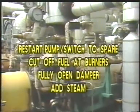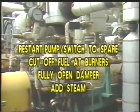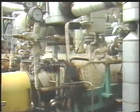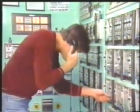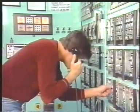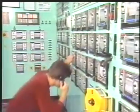Your first reaction should be to restart the pump if possible, or go to a spare. If you can't get the flow started immediately, you'll need to stop the input of heat by cutting off the fuel to the burners. The damper should be opened fully to allow the maximum amount of heat to leave the furnace. And steam should be added, which will have a cooling effect on the furnace. By cutting off the fuel and removing as much heat as possible, you minimize the chances of furnace damage. Once the situation stabilizes, you would want to call in maintenance and have the defective pump repaired.